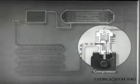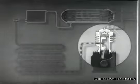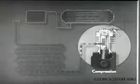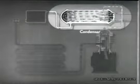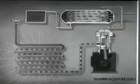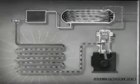Next, it passes into the compressor, where its pressure is raised again to the original pressure of the liquid refrigerant. It comes out as a hot, high-pressure gas. Then it goes into the condenser, where it gives up its heat and becomes a liquid at high pressure. It then flows back to the receiver and onto the thermal expansion valve for another cycle.